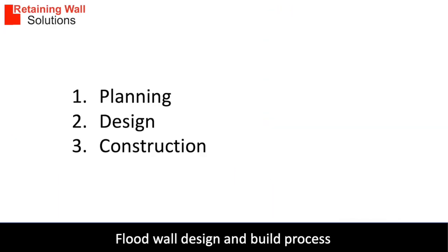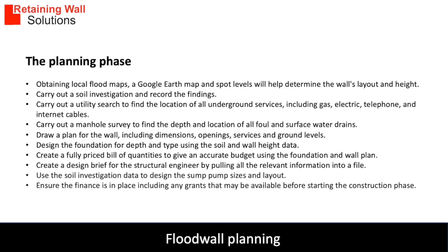We have supported many people to build flood defence walls and have developed a process to remove the complexity. The process is planning, design and construction project management. The planning phase: obtain local flood maps, a Google Earth map and spot levels to help determine the wall's layout and height.